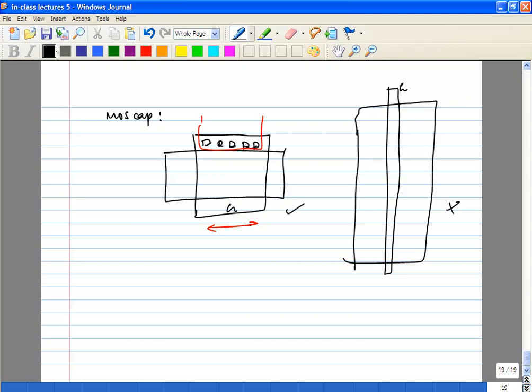And again, for all of these caps, because you're trying to get a lot of cap, let's say if you take a decoupling cap, more cap is usually always better. So you don't care about parasitic caps. Don't mind stacking up different metal layers on top of this. Don't worry about stacking metal layers on top of a decoupling cap. Extra cap only helps you, right? You want to minimize the resistance, so try to stack as many metal layers as possible.